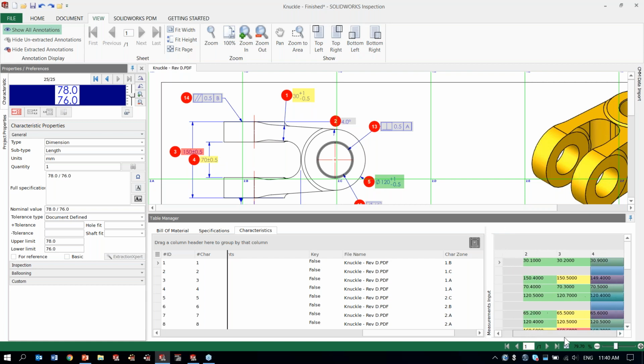So this is a great way because now we're able to see in time, using my samples, that some of those dimensions are actually going bad. As a quality inspector, that could mean that maybe some of my tools are not calibrated the same, or maybe some of the tools in manufacturing are getting worn out. So that means that some of those dimensions are going off. This is great information to capture, and all of this is captured inside my inspection document.